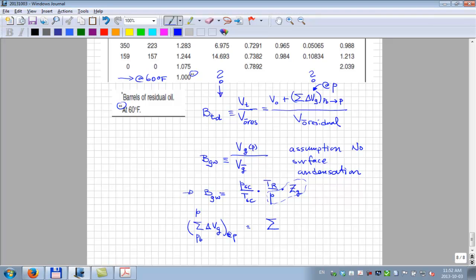So that'll be the sum from K equals the first release of gas in the second stage until a particular stage J. The moles of gas that have been removed, converted to standard gas volume, which would be the 23.68 number, for example, or 379, depending on your units.